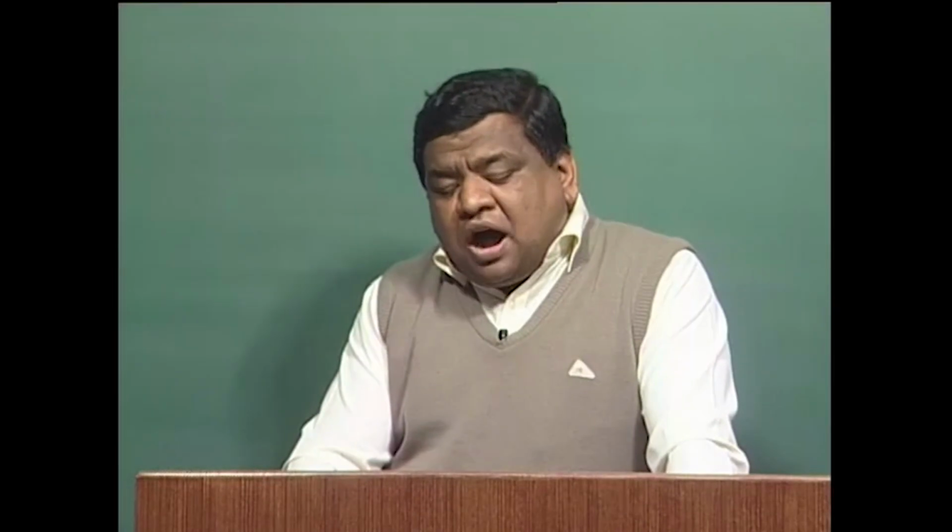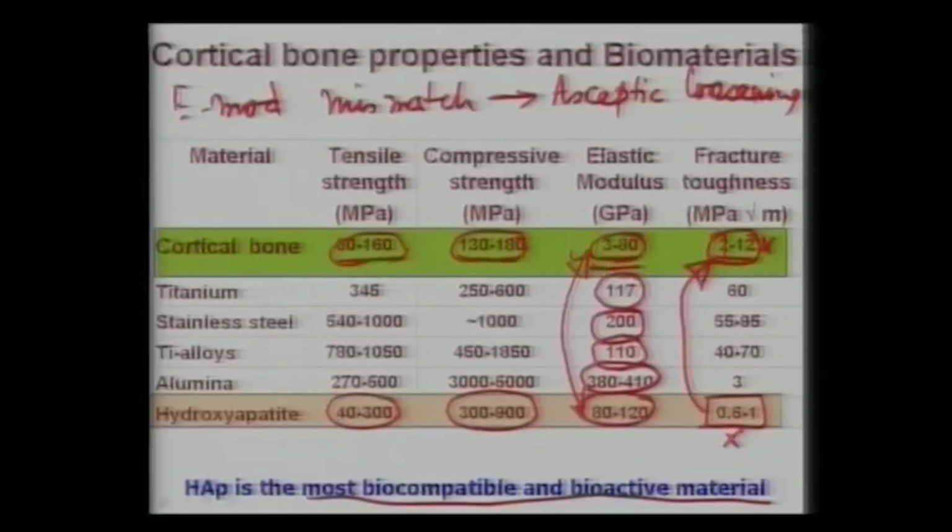So we do not want aseptic loosening to take place in the case of synthetic materials, and that is the reason I am emphasizing that elastic modulus mismatch needs to be avoided to the maximum extent possible, to get a better biomaterial with acceptable properties.